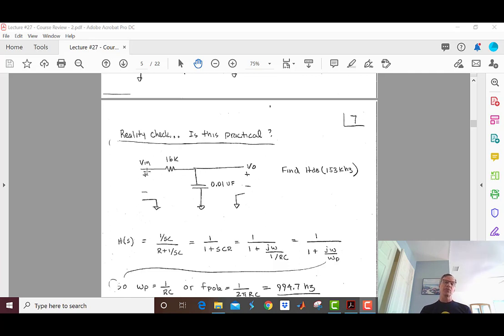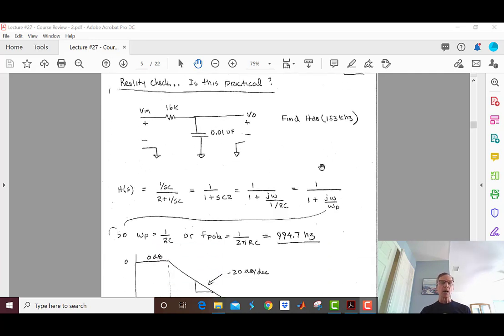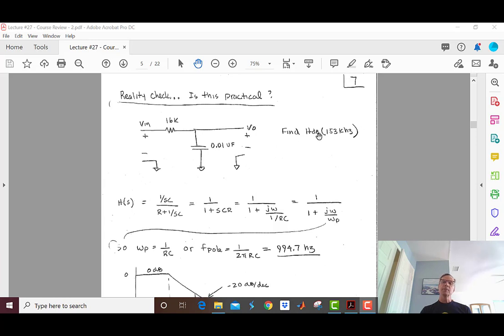And we put this little low-pass filter in to get rid of the birdie. And I might ask, oh, well, how much attenuation do you get at the birdie frequency? Well, I don't know, we just put in this little filter. It's worked in other places. And boy, when I hear that, I smell blood. That engineer may need to go work somewhere else. So let's work this real quick.